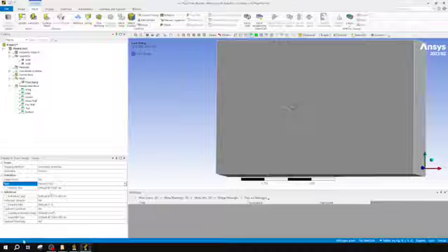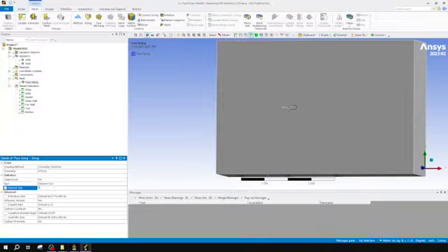I want something around 100th of the chord. So I'm going to go 0.001. I think that's 100th. That sounds like 100th. 10 to the negative 3. You'll see it makes the defeature size on its own. I'm perfectly fine with that.